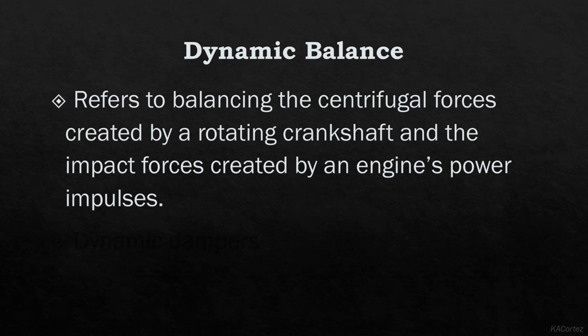Dynamic balancing refers to balancing the centrifugal forces created by a rotating crankshaft and the impact forces created by an engine's power impulses. The most common means of dynamically balancing a crankshaft is through the use of dynamic dampers. Dynamic dampers are weights which are fastened to a crankshaft assembly in such a way that they are free to move back and forth in a small arc.